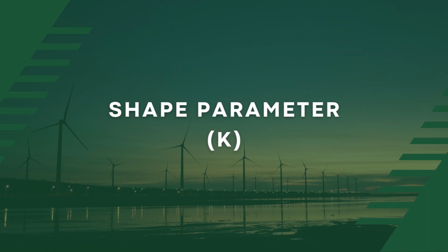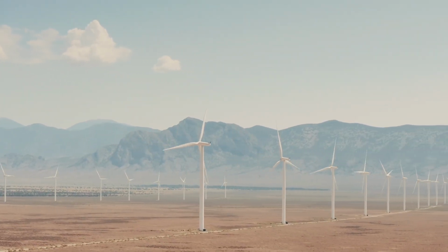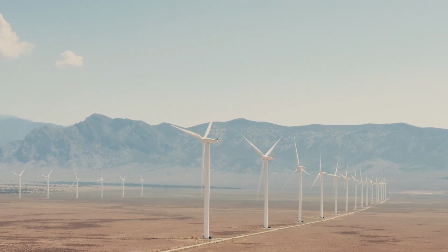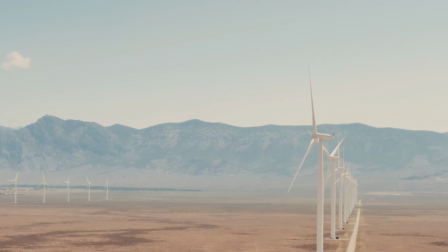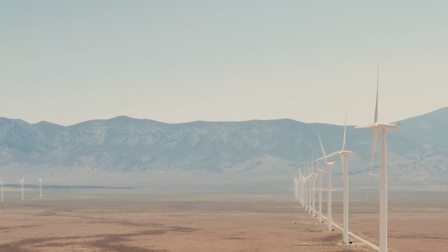The shape parameter of Weibull distribution determines the shape of the distribution curve. A lower shape parameter results in a broader distribution with lower wind speeds being more frequent, while a higher shape parameter leads to a narrow distribution with higher wind speeds being more frequent.